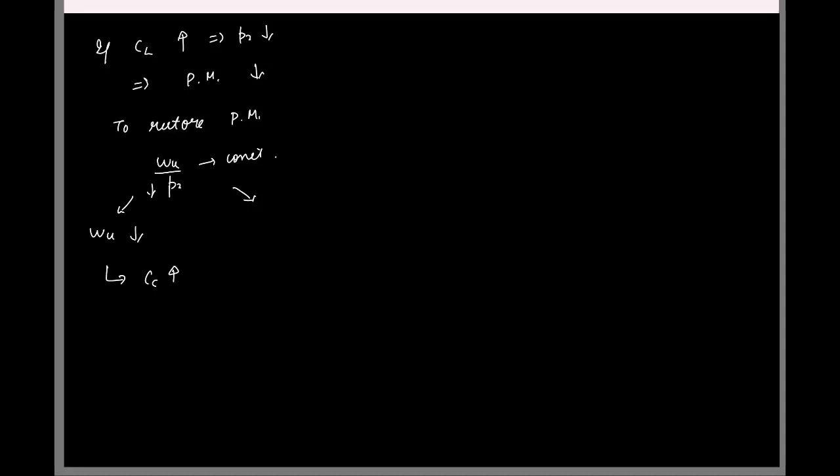Okay. So now let's say I want to take the other route and increase P2. I want to do that because I'm reducing omega u, and remember, omega u determines the speed of the op-amp. Approximately that decides the closed loop 3 dB bandwidth. So you don't want to reduce the speed of the op-amp. I want to keep omega u constant.